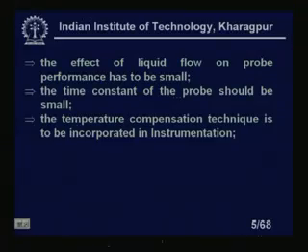So we should not give much emphasis to the time response, but sometimes we have to take some action. Suppose the dissolved oxygen concentration or partial pressure of oxygen suddenly falls, and immediate action has to be taken. In that type of situation, if you have a lower time constant or a fast sensor response, that is always helpful for taking action.